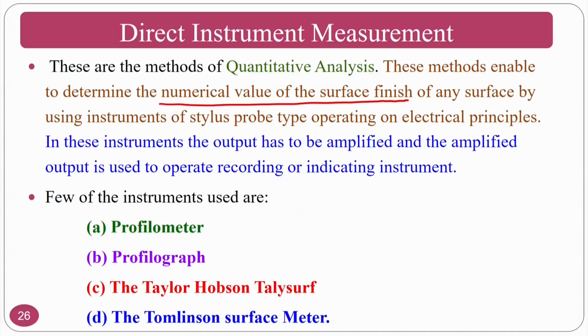Nowadays there is a direct probe method where a stylus reciprocates, which you have seen in the measurement technique where I explained evaluation length and those things. The probe will reciprocate on the surface and give you the quantitative value.